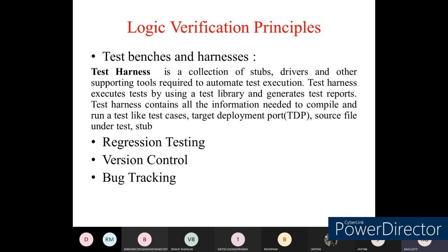In regression testing, we use different scripts written in a high level language in order to run larger test benches. This regression testing involves performing simulations that can automatically verify some of the functionalities which are directly or indirectly connected to each module.